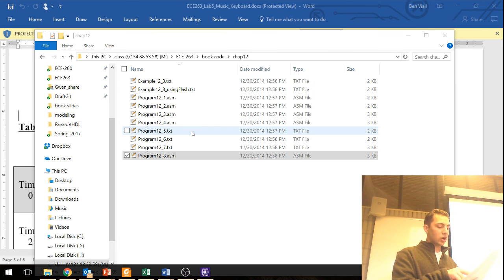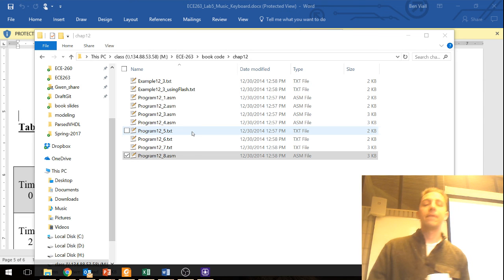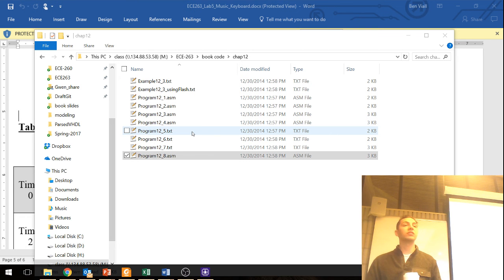It wasn't called CS. It's a good example here. We didn't have force output compare 0A and 0B. We just had force output compare because there wasn't two channels. So it's something to look at. So you can convert these over to 328P compatible code relatively quickly.